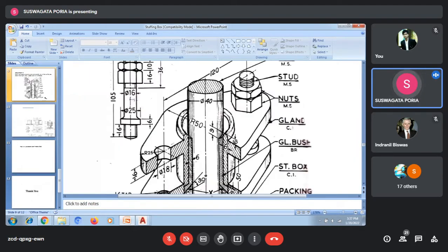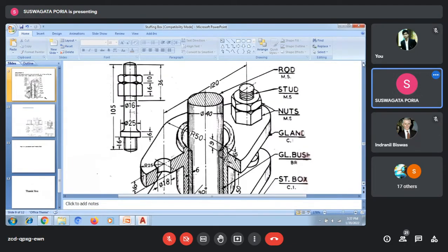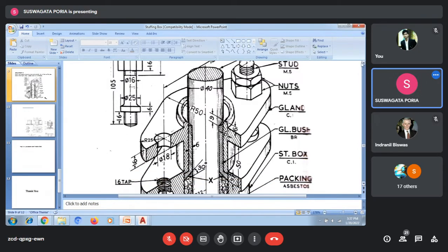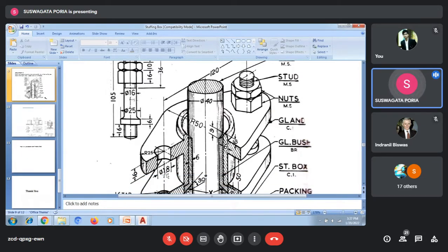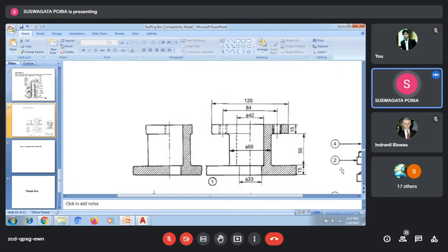If you come here, you see, this is how much. Wait, this is how much. M16 means major dia is 16. Okay, major dia 16. But the hole dia is given 18. This is the same information which I was talking about here.